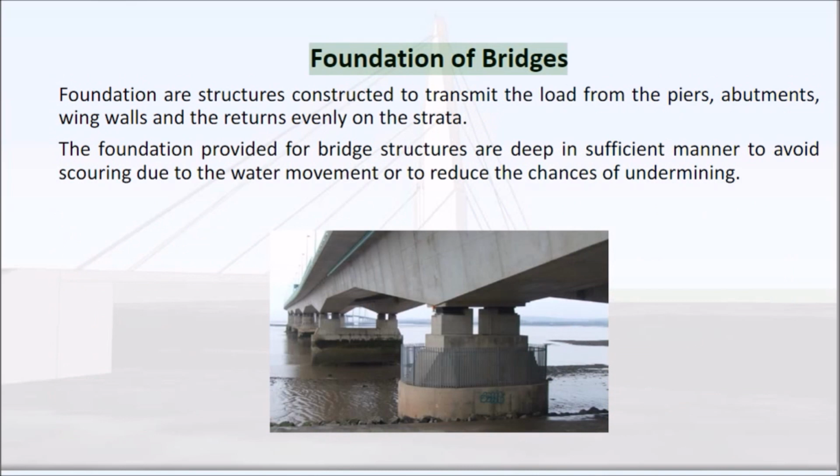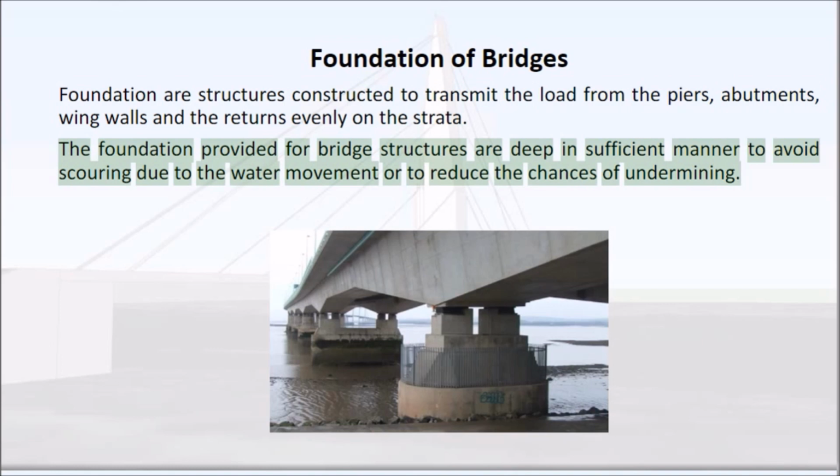Foundation of bridges. Foundations are structures constructed to transmit the load from the piers, abutments, wing walls, and the returns evenly on the strata. The foundation provided for bridge structures is deep enough to avoid scouring due to water movement or to reduce the chances of undermining.